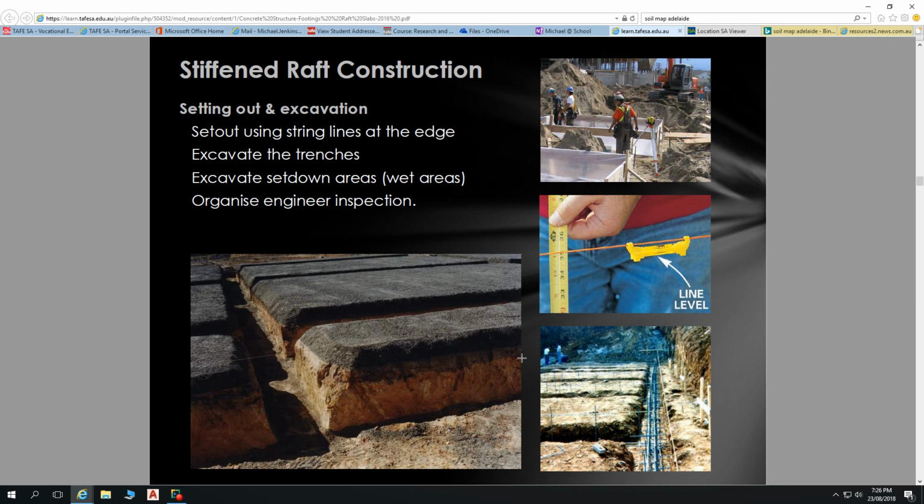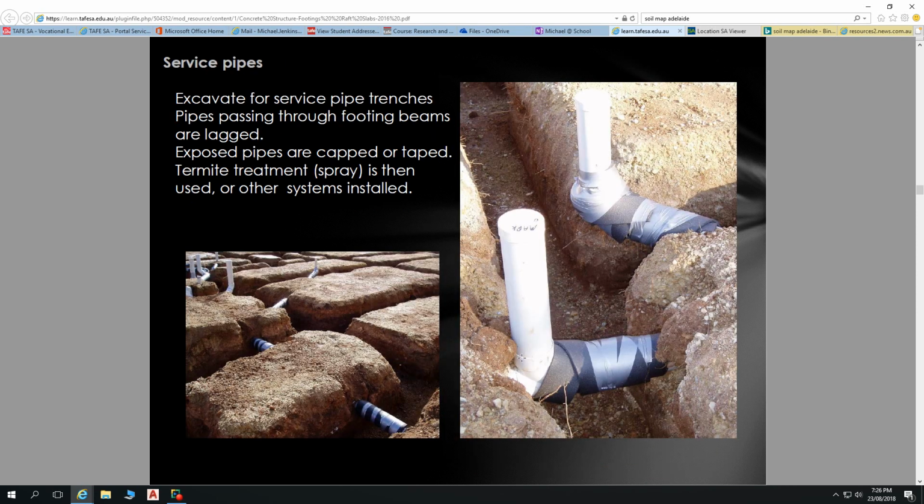That's a lot of tippers. So 20 ton in each. So that's a lot of loads. You've got to pay for that to be transported somewhere. You've got to find a site close to where you're doing your excavation that wants to take your fill as well. So that's another reason why you want your footings to be accurate and to be neatly formed.